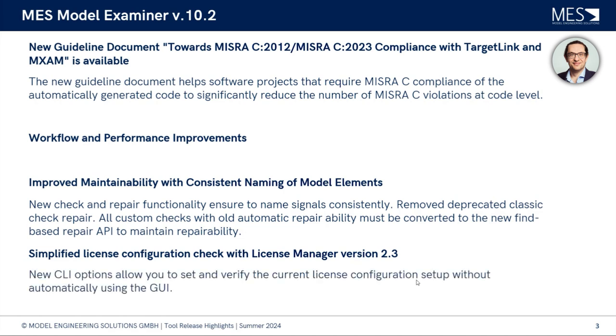Because with the latest update, you can now set and verify the license configuration setup without starting the tool over the graphical user interface, so that you do not run into different errors than when the tool is already running. And it is now possible with the latest license manager to check for Flexera system variables.